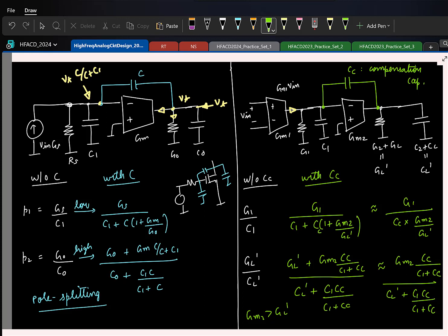So in this circuit, in addition to the 2 poles that we have written here, is there something else? First of all, how many poles will we have here? I can only set 2 capacitor voltages independently, because if I initialize these 2 capacitor voltages, this is automatically defined. So 2 poles that we have written. Is there a 0 here? Yes. We can short this capacitor, the output is non-zero. And intuitively also, we have currents from 2 different branches with different phase shifts getting added. And we also computed the 0 here.